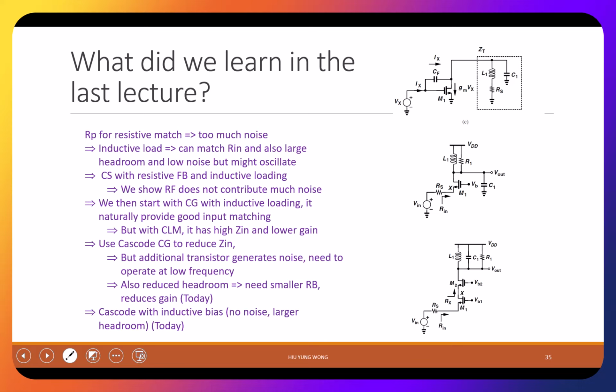Some of you got close to 4, but it seems to me maybe just because you have a smaller inductor, because those people have a larger transistor, so larger capacitor. Some of them also tried to add a large C1 there, and because our inductor actually has serious resistance, I feel that's the reason they get lower noise. But in reality, when you add a capacitor, although the area is larger, you also have resistance.